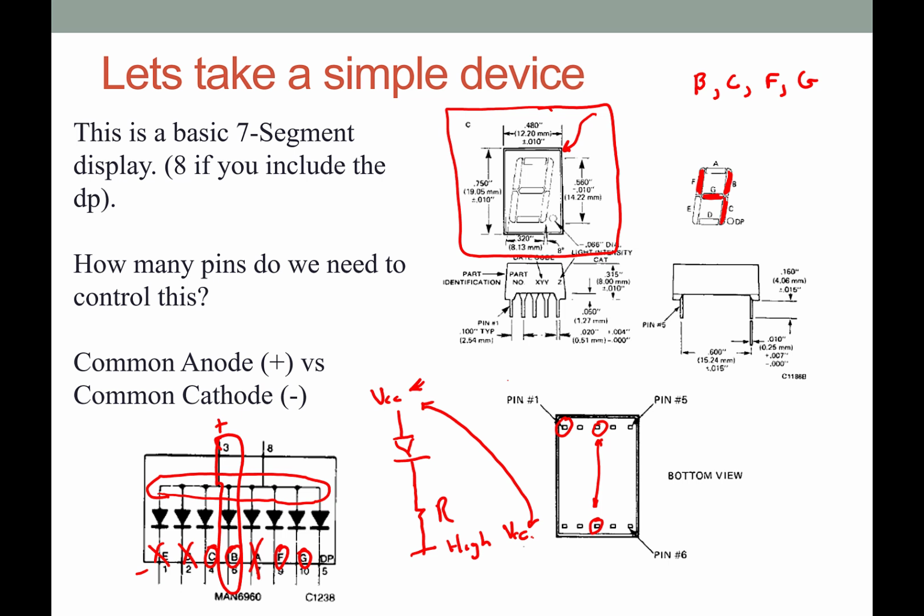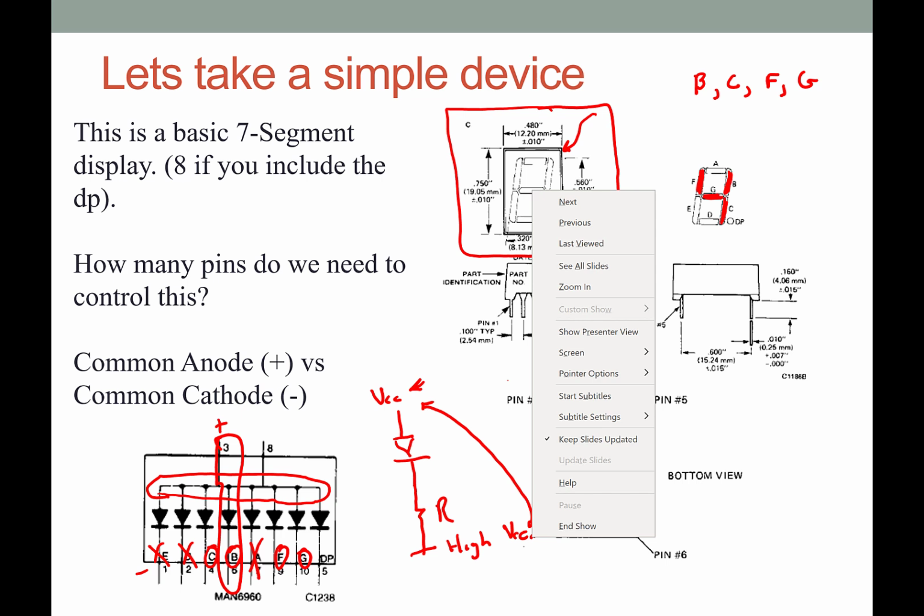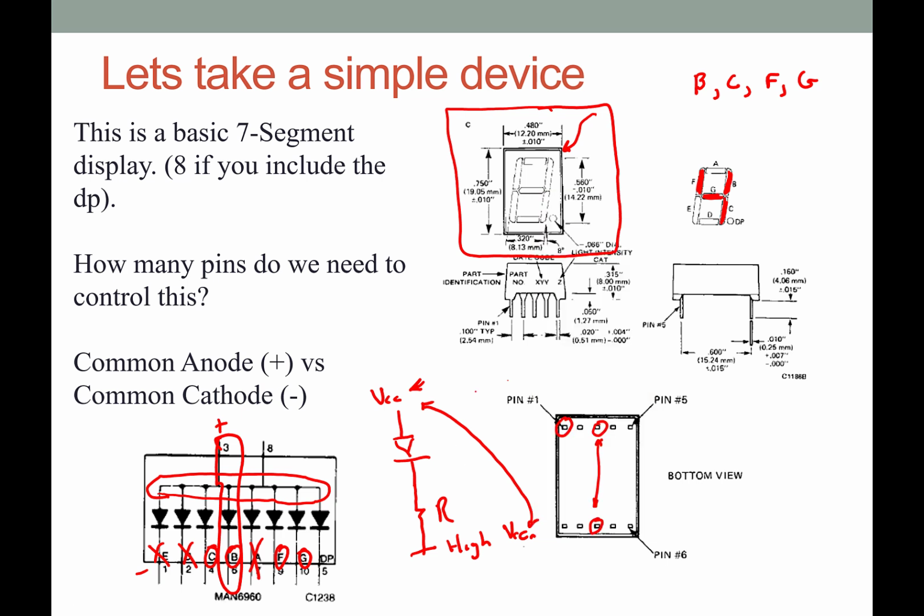So if we have VCC and VCC down here, then there's no voltage drop net across that diode, so this would be 0, the diode can't turn on, the current in the path would be 0, and it'd be done.